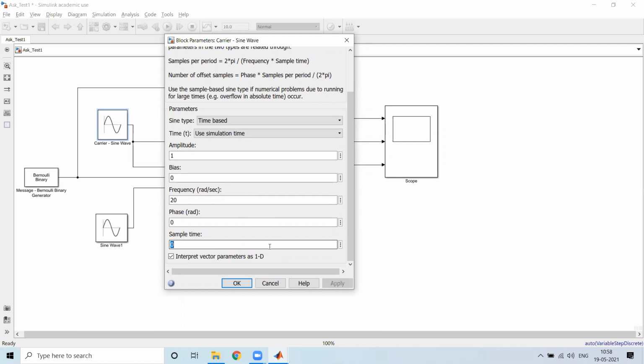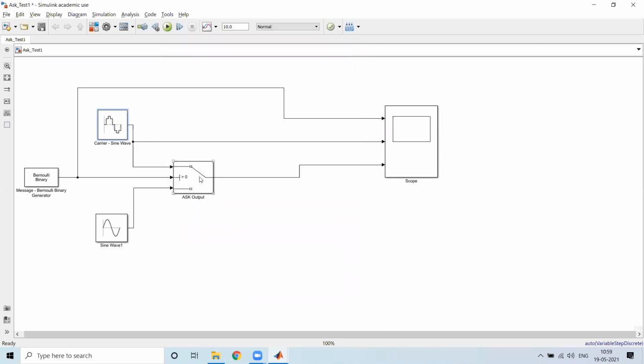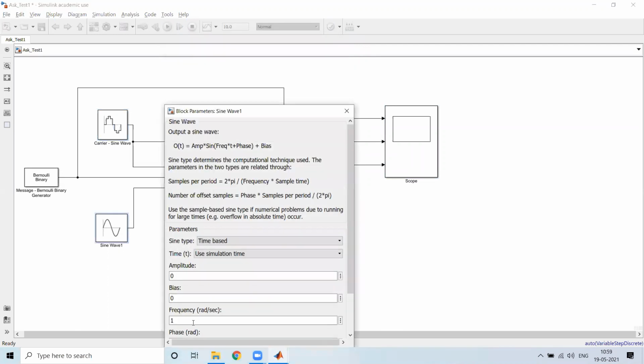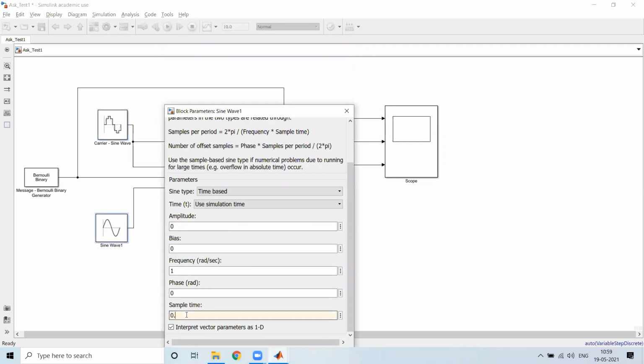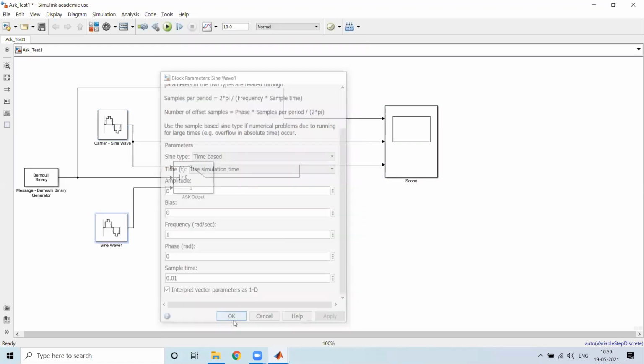So what I'll do is I'll try to change the sample time. Here, what happens is you are taking the samples from the system and then generating the sine wave. Because of that, the distortions you're observing will be seen. So I'll just make it 0.01. Even this one, if I have to utilize it later, I can. But since it is 0, no need to worry.